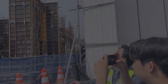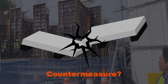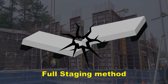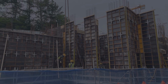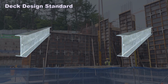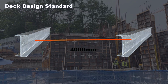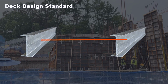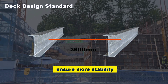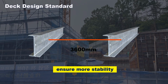At our construction site, we have devised one countermeasure to prevent collapse due to beam deflection when constructing the beams and floor. It is the reinforcement of the full staging method. According to the deck design standard, full staging method reinforcement is required when the distance between columns is 4,000 millimeters or more. But at our site, full staging method reinforcement was carried out from 3,600 millimeters or more to further ensure stability against collapse before and after the concrete placement.